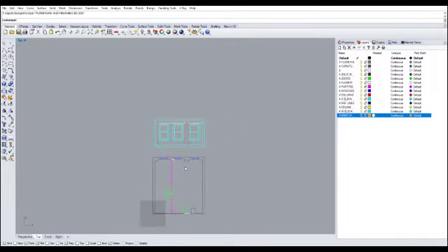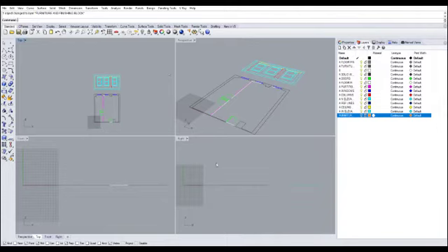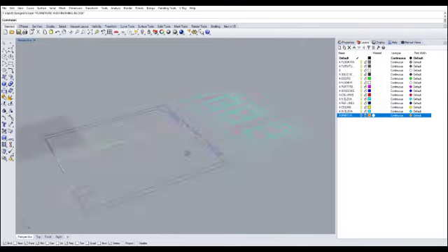Now, before we start making this into 3D items, you want to be in the right view for 3D, and top view is not. So if you want to change the view, all you have to do is double click this little tab where it says top, and then our four separate views appear. This, your perspective view, is your default 3D view. And of course there's a right view and a front view, the other three orthographic views. So let's go to the perspective or 3D view by double clicking on the view tab.